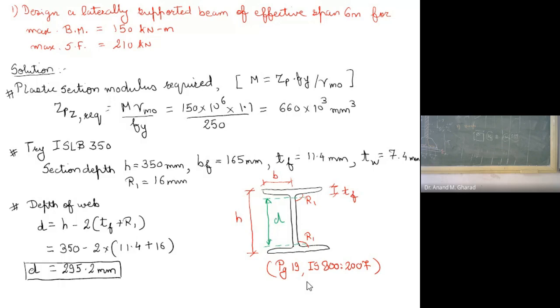Look, where have we seen channel section as a horizontal member? Plain horizontal member and the cross section is channel section. Where have we seen it? We just completed purlins in trusses, isn't it? Purlins, they are horizontal members, so you can also call purlins part of beams. Function is same, they are resting on two supports, two or more supports, whatever it may be. And what load do they carry? In the transverse direction. So you can consider that to be a beam, but the cross section is C type, unsymmetrical.